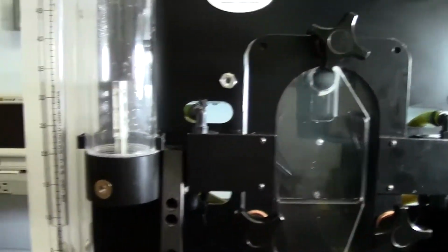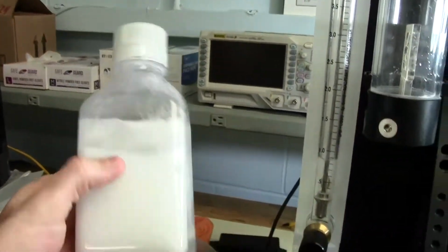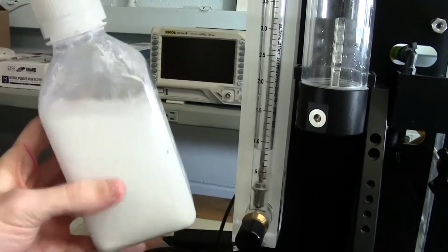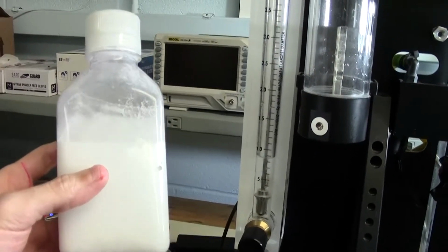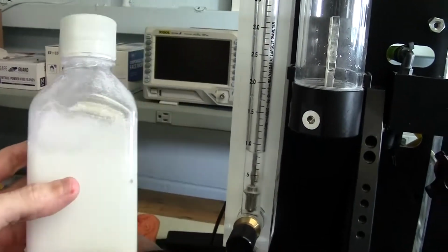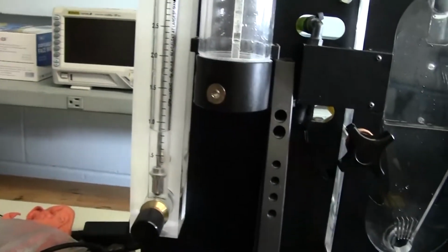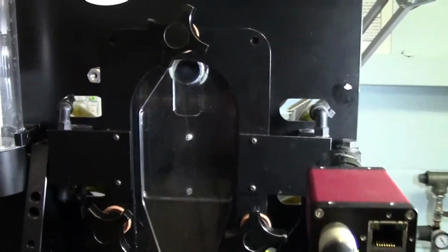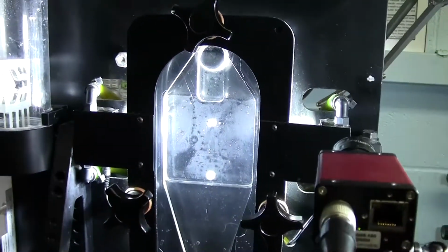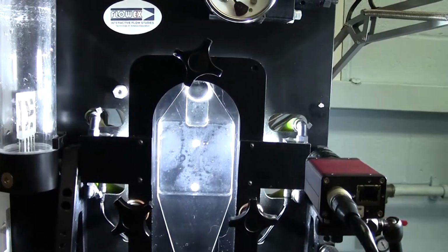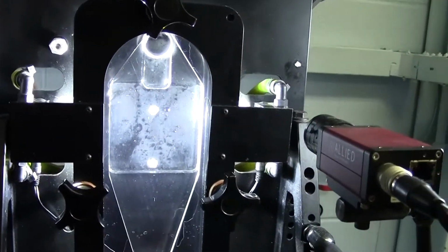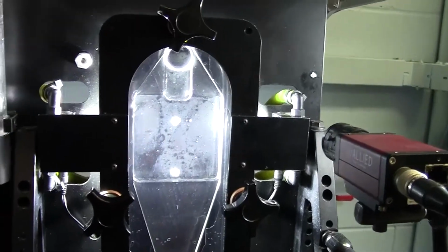So for the PIV analysis, we'll put some PIV particles in the water. You can see them here. This looks like milk, but is actually very small particles dissolved in water. So we will put some of this in the water, and then we have LED lights on both sides of the test section. We can turn them on to illuminate the flow, and we also have a camera to get PIV images of the illuminated moving particles, right?